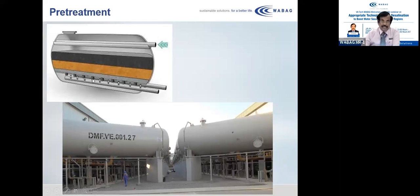In the process, the bigger particles get collected here due to the bigger voids in the anthracite, and smaller particles get collected here. So this has a filtration duration of around 24 hours. Once in 24 hours, it is backwashed by admitting filtered water from the bottom through the nozzles. Fluidization of the media takes place, and that releases the entrapped particles, which are carried out through the outlet pipe, and then taken out and dumped outside as backwash water.